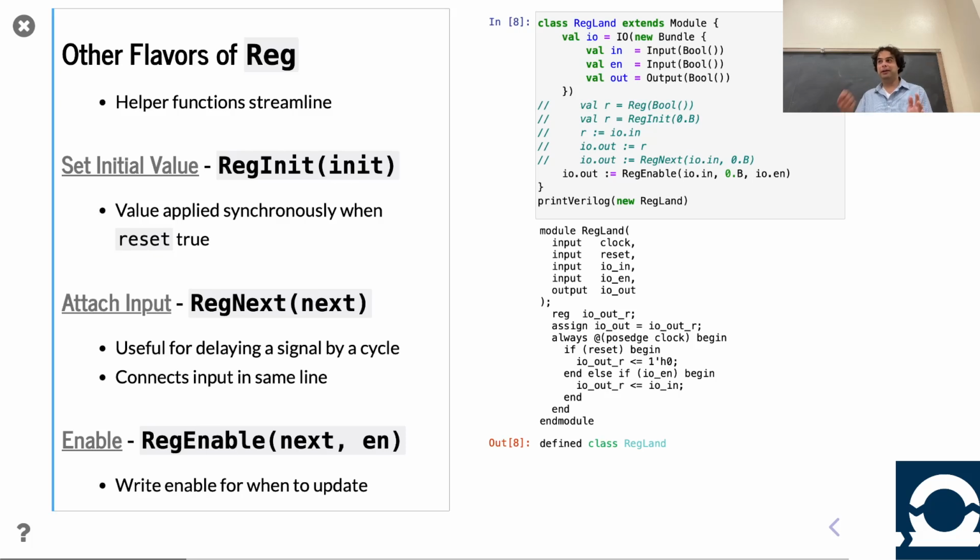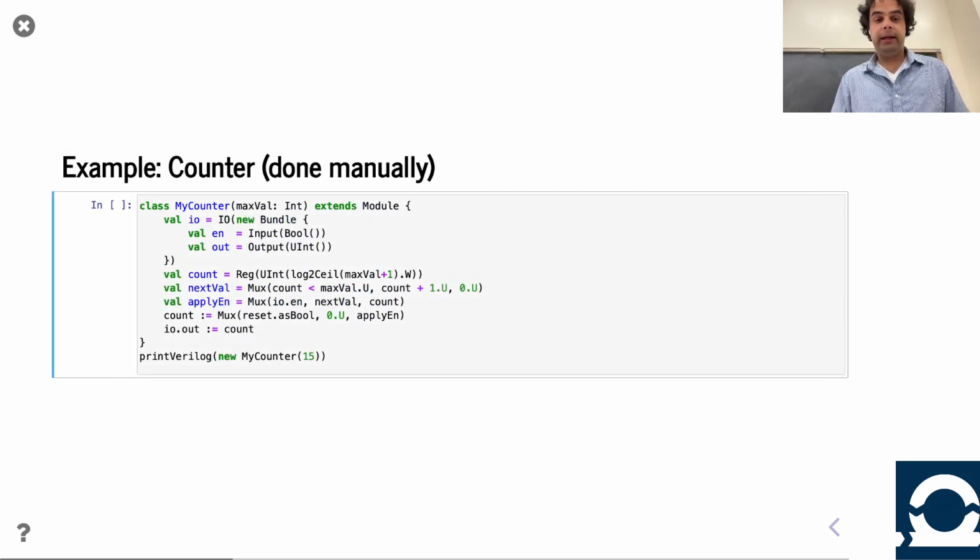So it's a very niche real world constraint, not required for this course. But between synchronous registers on positive clock edge plus the ability to do asynchronous reset, which we've linked to documentation, that covers like 99.999% of registers in industrial practice. But yes, in certain cases, people have that really fast flop they need, and in that case, they can use a black box. Cool, great questions. Okay, let's keep going.